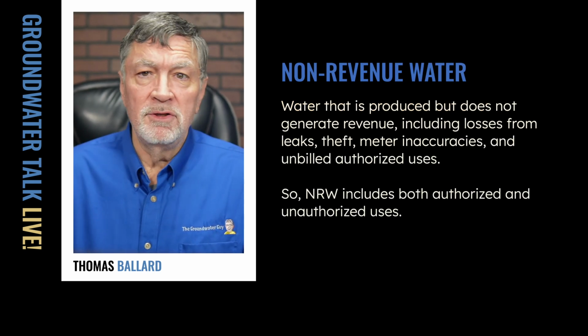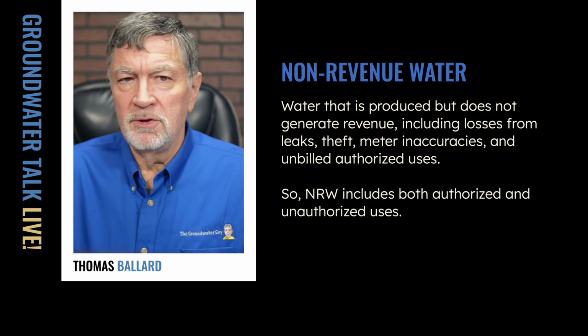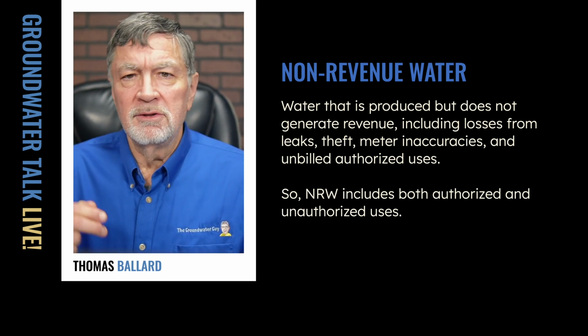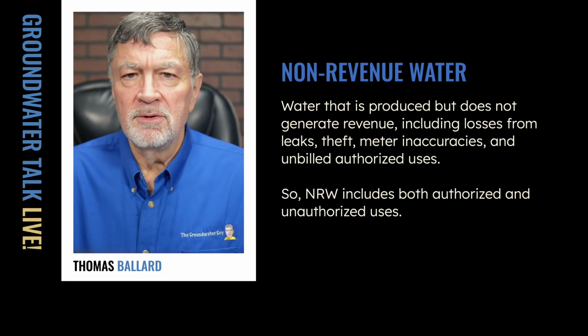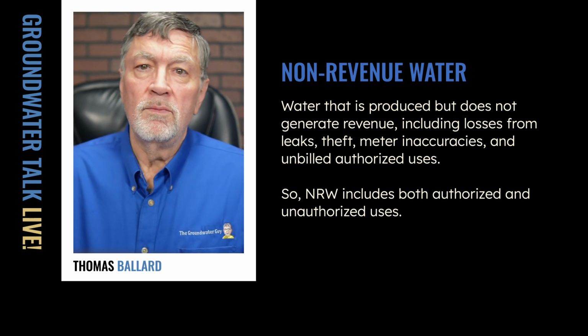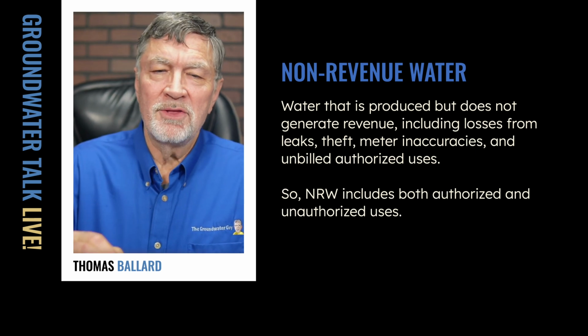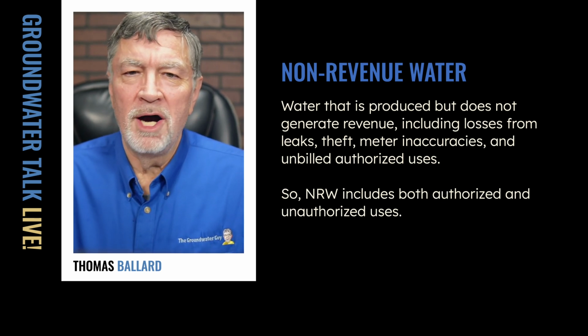All right, non-revenue water. That's going to be water that's produced but does not generate revenue, as we discussed earlier, including losses from leaks, theft, meter inaccuracies, and unbilled authorized uses. So once again, note, we have authorized and unauthorized uses of non-revenue water.